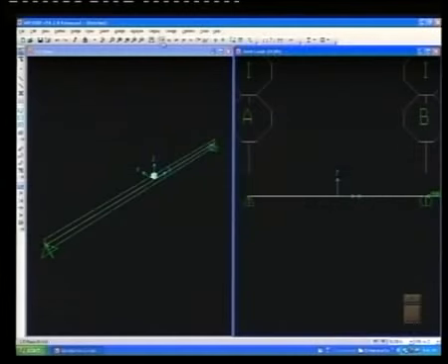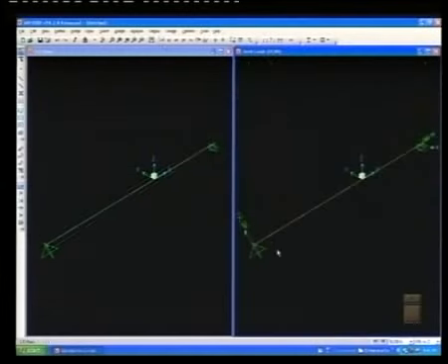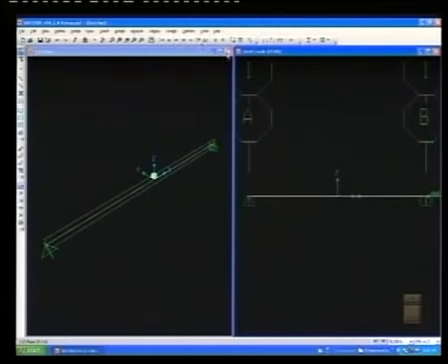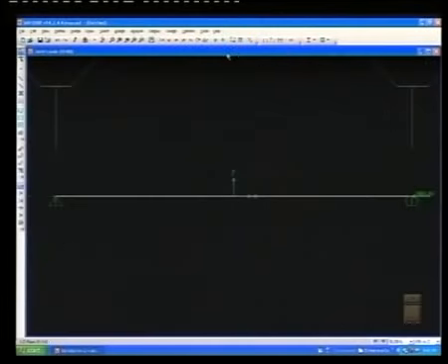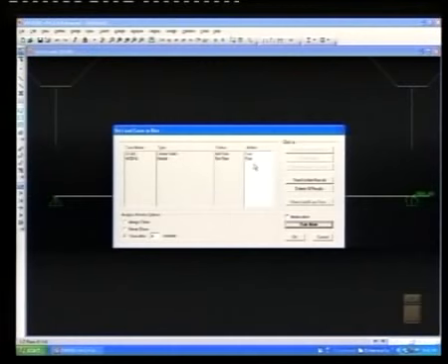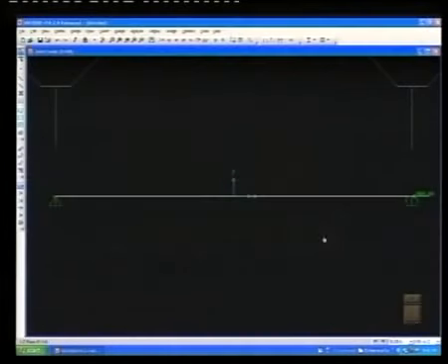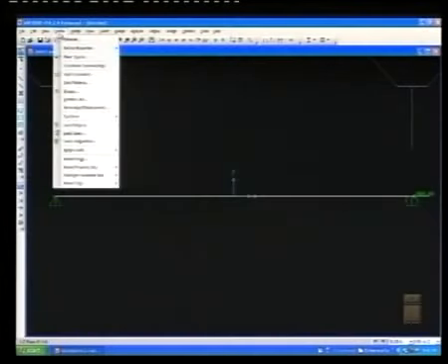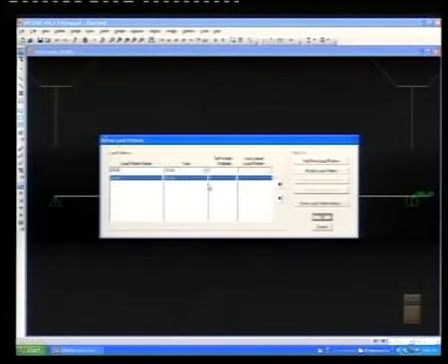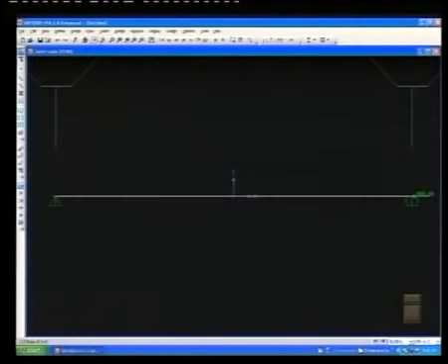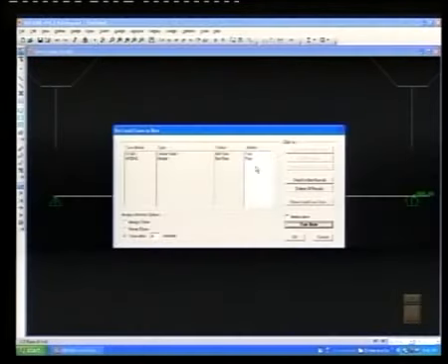Look at it in 3D. You will find that bending moment like this, bending moment like this, produce uniform bending moment. We can return to XZ, close this, and do analysis and design. Before doing analysis and design, let us remove the dead load. We don't want the dead load to be included in the calculations. Now we have a beam column. We can run it.